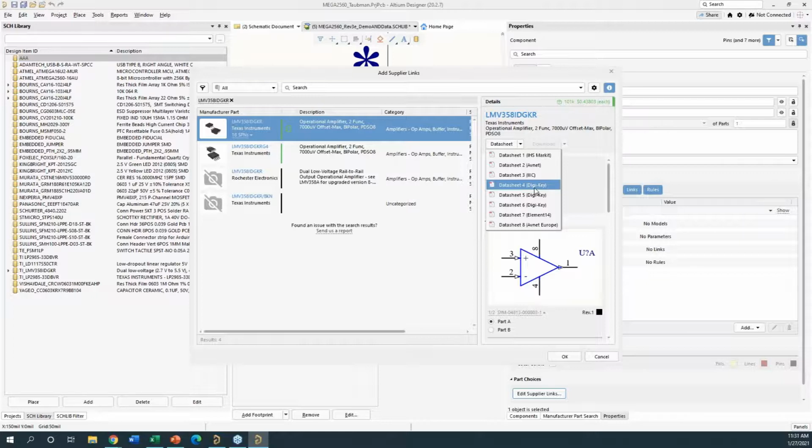And to me, it shouldn't do that necessarily. I know why they do, because they don't want people asking for it, and they don't want the secondary market to constantly sell these things. They just want to get them off the streets in a sense. But on the other hand, it's really important for you to have that data sheet, because how are you going to find the equivalent of it if you don't really know what the base characteristics are to begin with? So that's why I'm a big fan of always keeping a local copy of the data sheet around.